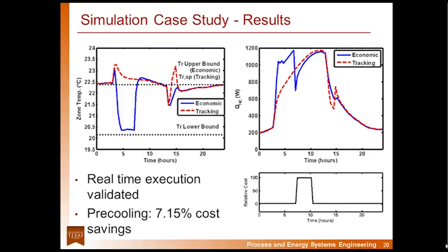And this saves money for the HVAC system operation. The effects seen here are a bit small, so I mean that the temperature rises really quickly once the pre-cooling period ends, once the air conditioner isn't doing extra work to keep everything cool. This is because the thermal facade lab does not have anywhere near as much thermal mass as a large home or office building. So these effects would be exaggerated in more practical settings.